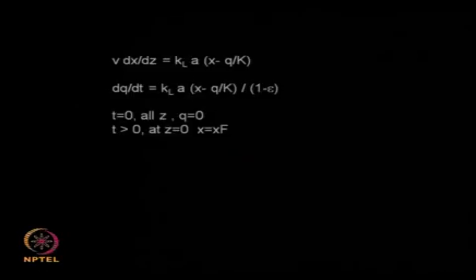Stirred tank, everything is stirred, so we have a bulk concentration, whereas in a tubular we do not have back mixing, that is why the concentration of the solute along the Z axis also will vary, in addition to varying as a function of time. So a stirred tank has complete back mixing, whereas tubular has no back mixing.